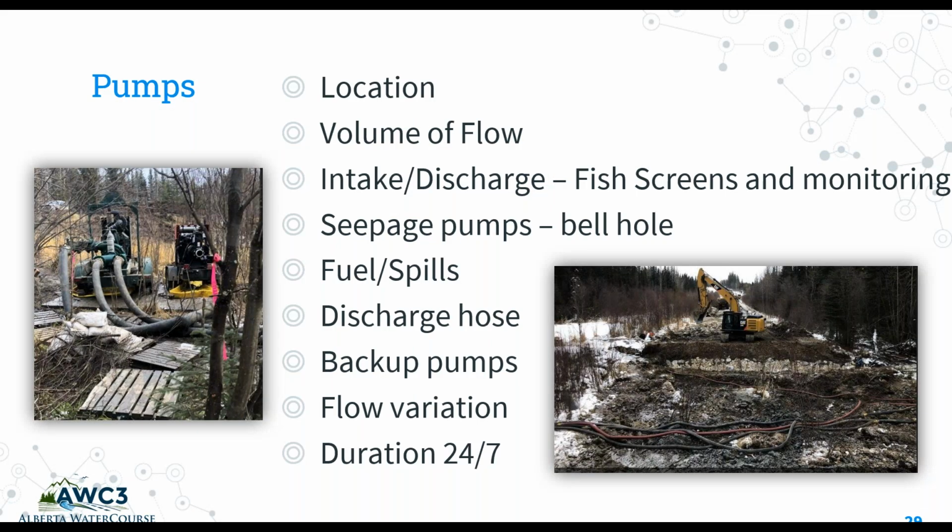Pumps, so if you decide to go with the pump route, you need to think about the location of your pumps, the volume of flow that your pumps need to handle, the intake and discharge. So fish screens on your intake, monitoring your fish screens, your discharge, sediment and erosion issues. If you're pumping with an 8-inch pump, you'll want to make sure you are controlling your discharge so you're not affecting the creek downstream.